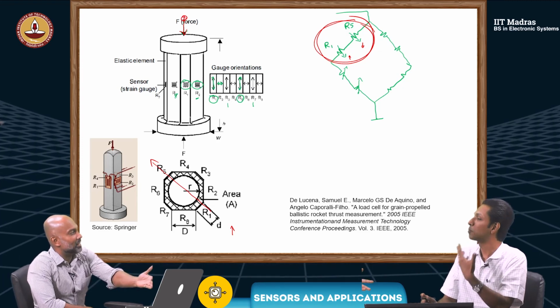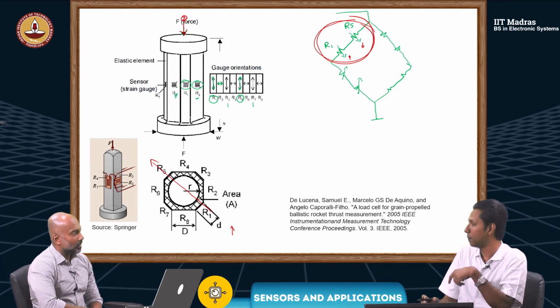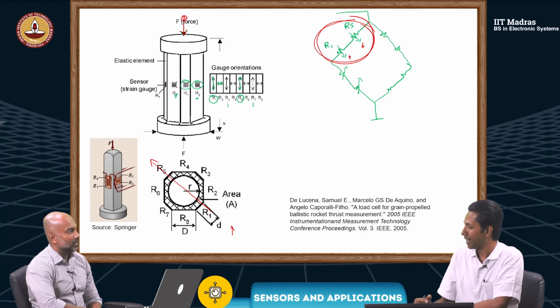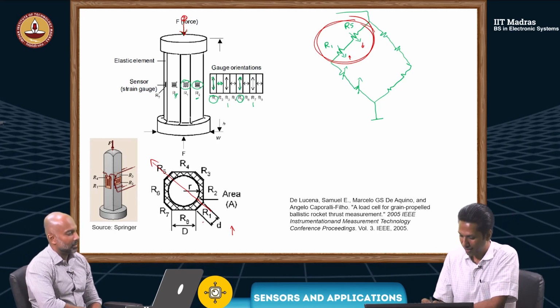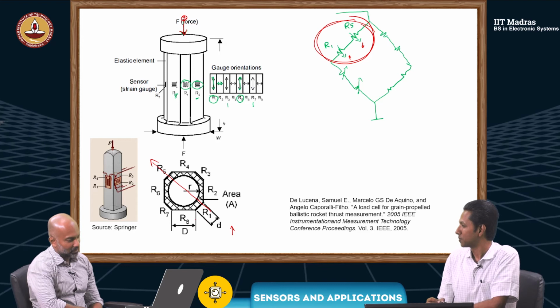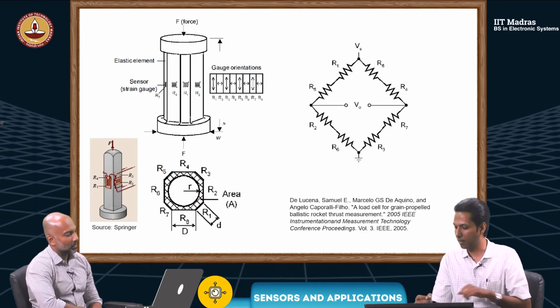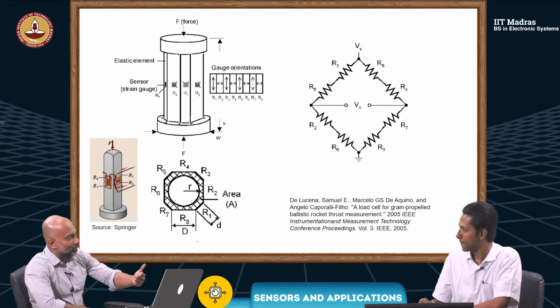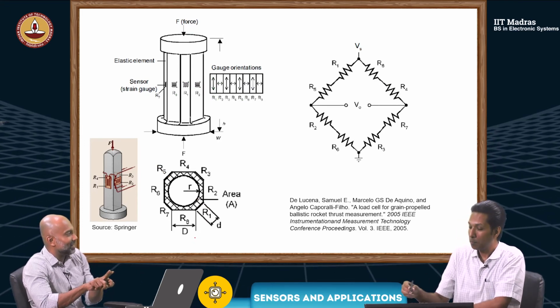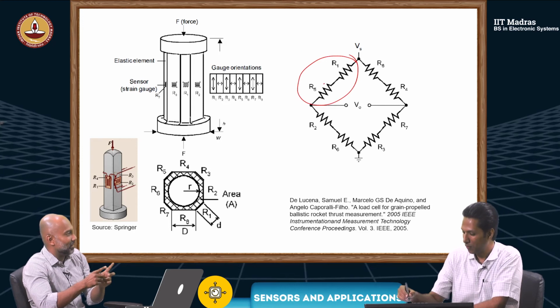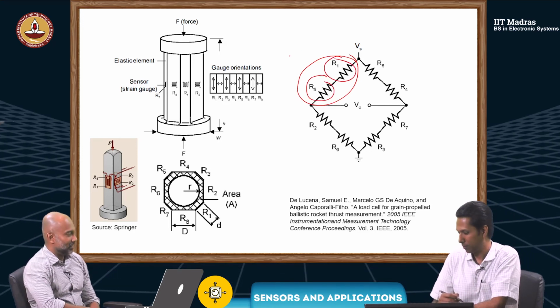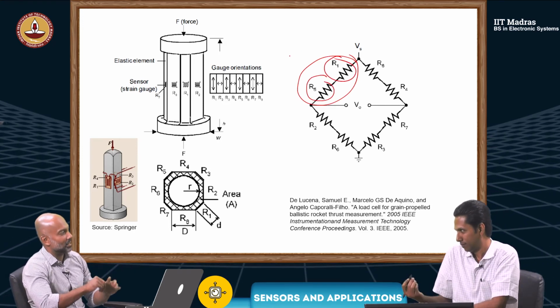Now that bridge arm is not sensitive to this bend. Yes. It is sensitive only to the vertical. Vertical. Yes, yes. So this idea is expanded to other branches. I mean, it is sensitive, but they cancel. Yeah, right. The branch by itself is not sensitive, while individual elements are sensitive. But they are in the opposite direction, so they cancel.